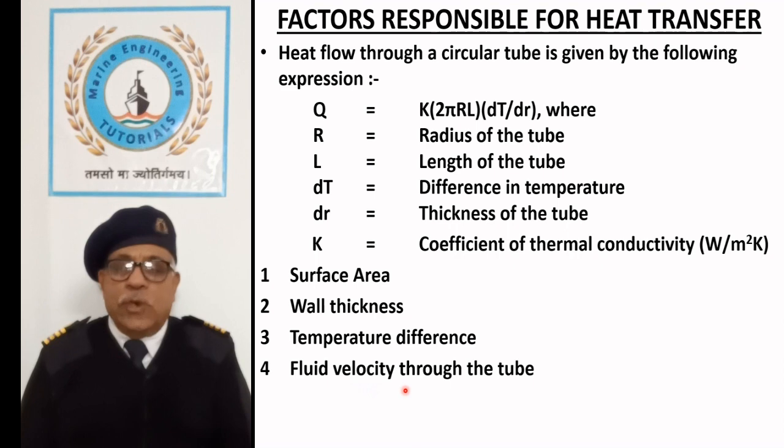Fluid velocity to the tube. Laminar flow with velocity below 1 meter per second slows down the heat transfer rate and causes deposits on the tube walls. On the other hand, turbulent flow improves the heat transfer and prevents deposition of the debris associated with the coolant on the tube walls. However, velocity exceeding 2.5 meter per second causes erosion of the tube material, which should be avoided.